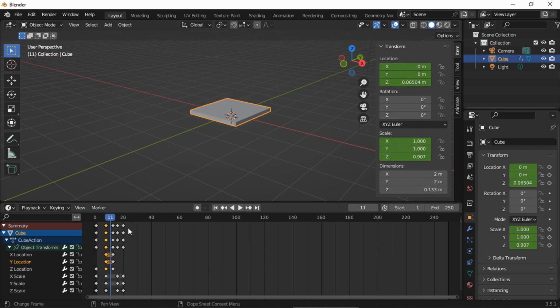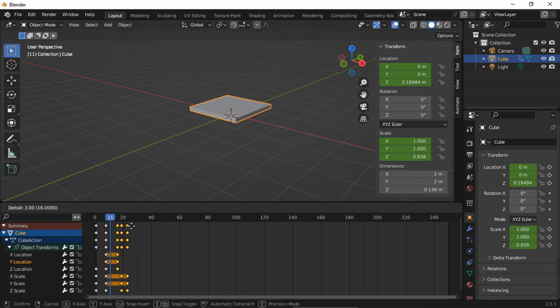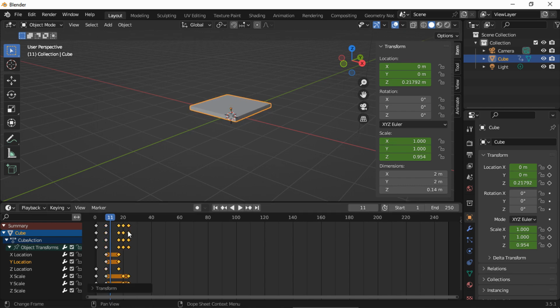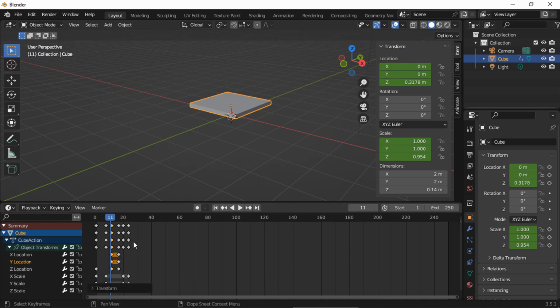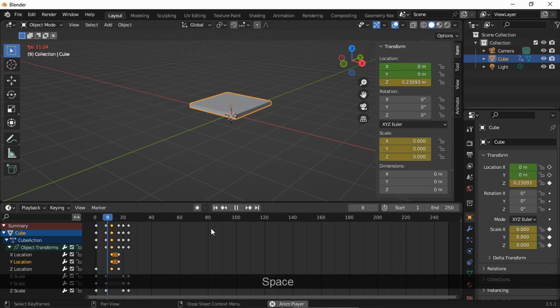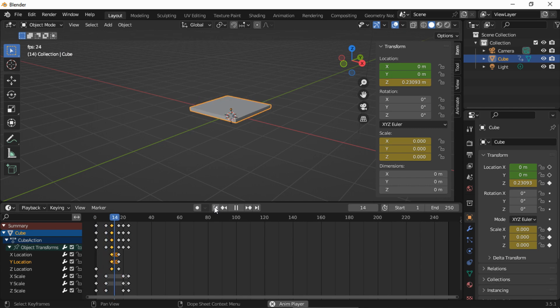Let's move these keyframes. Now the scale and location are animated in unison, so we could move some keyframes to break that monotony. So I'm gonna move these location keyframes only, without moving the size keyframes. Now the base turns big first and then moves down.